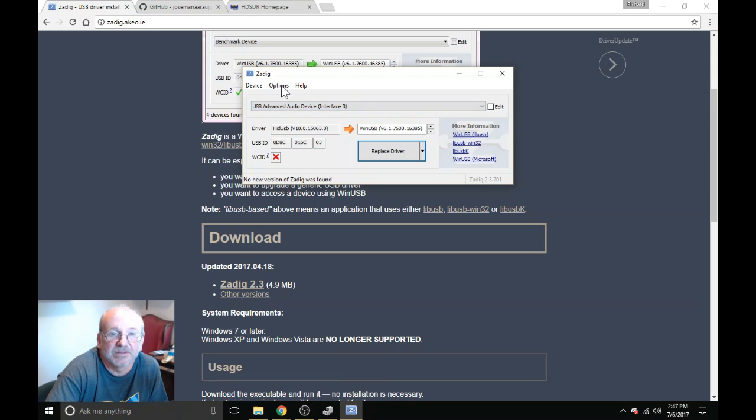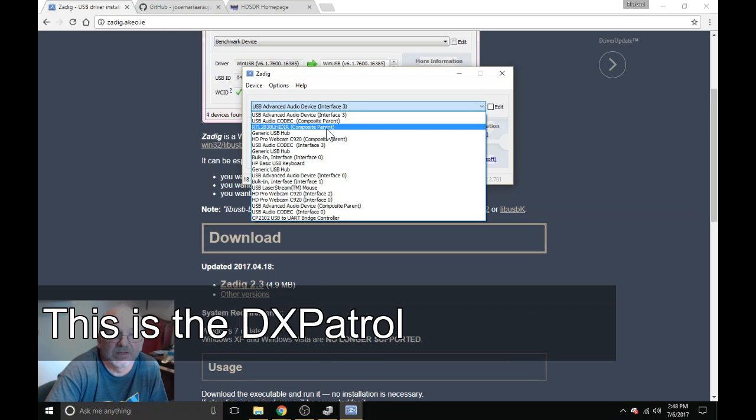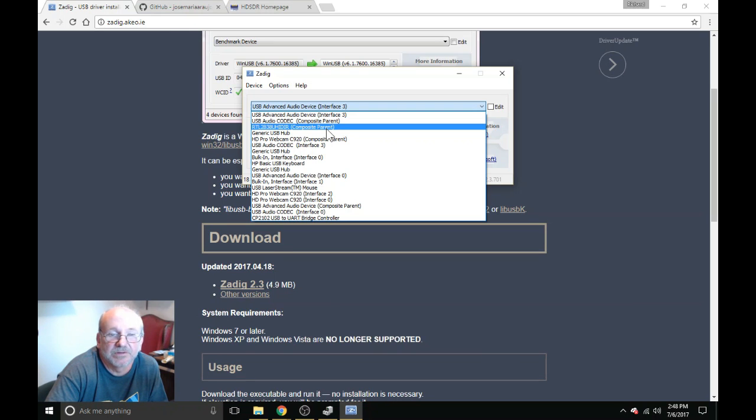So let me take a look. Another thing I want to do is ignore the hubs or composite, and let's see what shows up underneath here. This is what I'm looking for, RTL 2838, this right here, and I don't see it anywhere else. When you're looking through these lists, just pay real close attention. I've done this numerous times, and I could swear that some installations are different than others. And I've done it with the rtl-sdr dongle, and it definitely shows up as a bulk-in device.